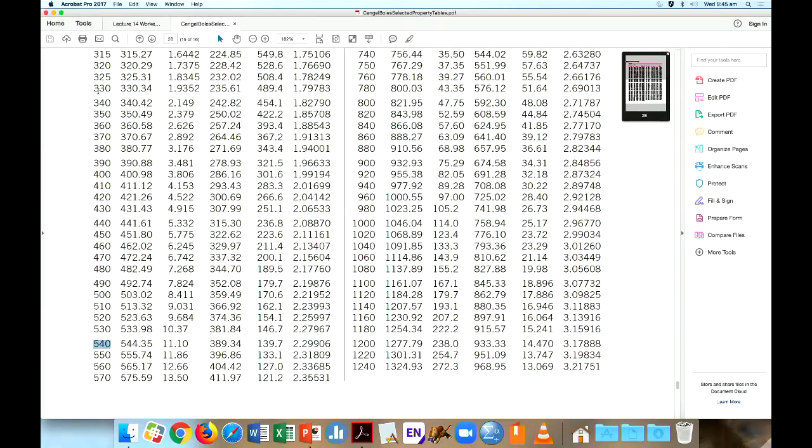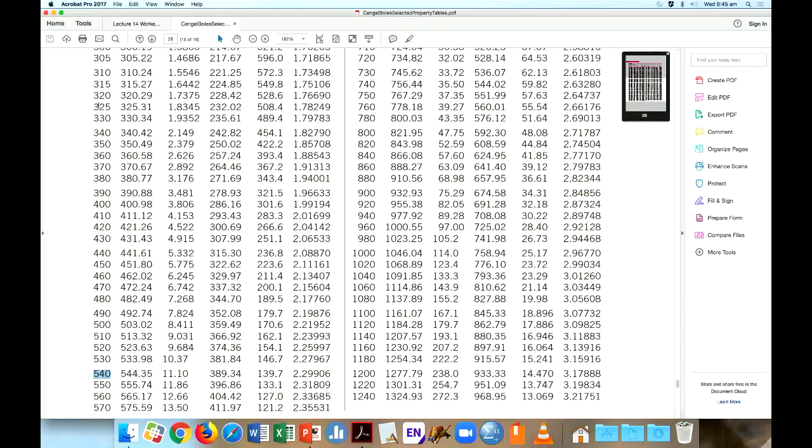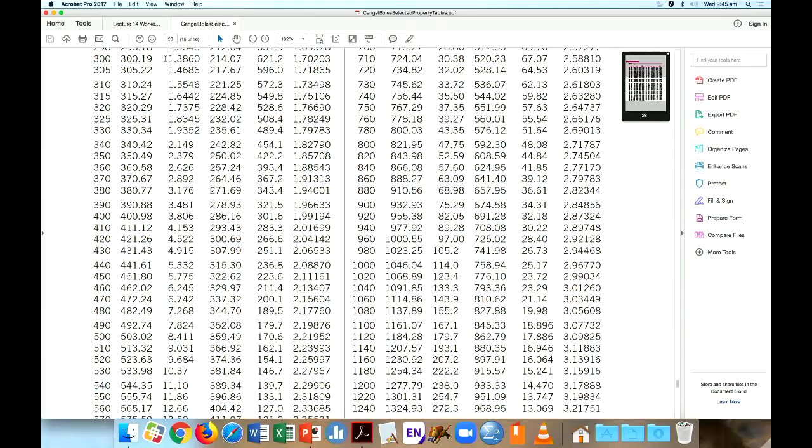So we had from 300 to the reduced pressure, then using the pressure ratio to take me to the new pressure ratio for the isentropic process only. I can only use PR2 on PR1 equals P2 on P1 for an isentropic process. I can get enthalpy and I can get temperature.